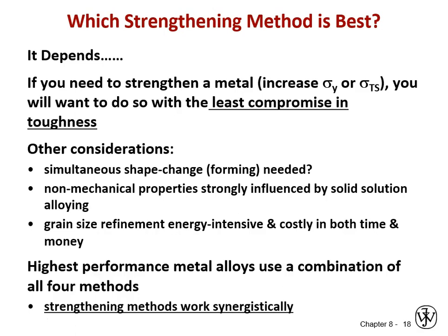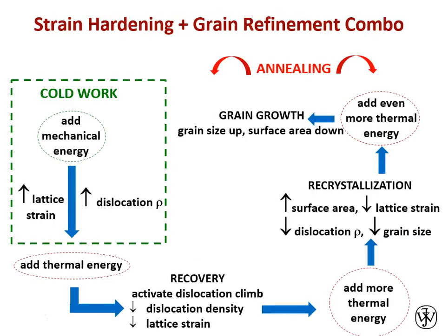On the good side, you don't have to use just one. You can work harden an alloy as opposed to a pure material. You can use a combination of work hardening and alloying and grain refinement, and you can go in and put a dispersion of fine ceramic particles in almost any material and give it some strength at higher temperature. So quite often your cheapest and your most effective solution will be a combination of these strengthening methods. And those, again, may or may not be the cheapest. Maybe they will, but they will generally give you the best combination of properties.